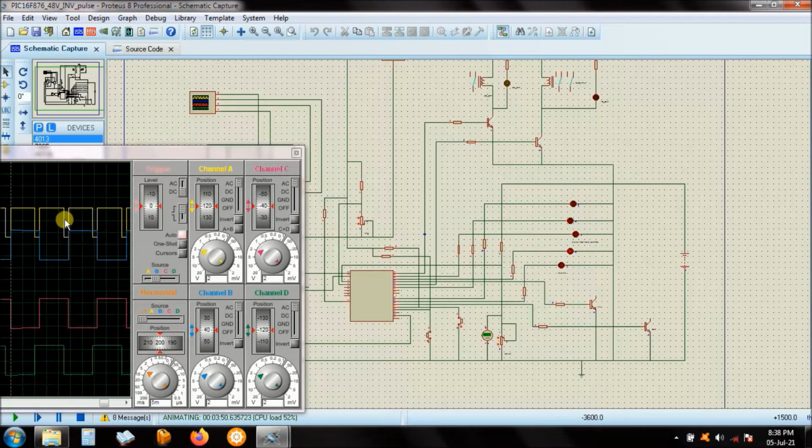Same signals output, but here the LEDs don't change. They just show you the level of the supply of the battery. Actually, these LEDs are just showing the level of the batteries, but the error signals are still the same. These two flickering, showing you the battery is now getting lower, and the bars are coming on, and then it comes on for some time and then goes off. And if these two are flickering alternately, it means there is an error. The inverter will shut down. Right, okay, that's for the battery side, similar to the module side.